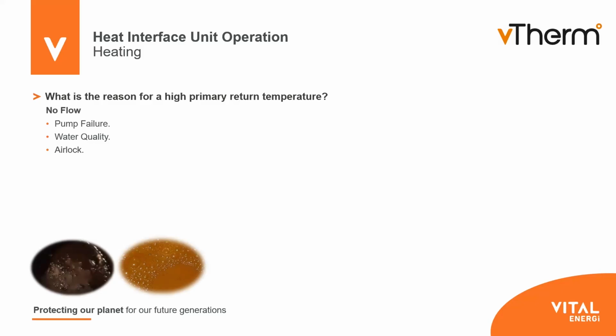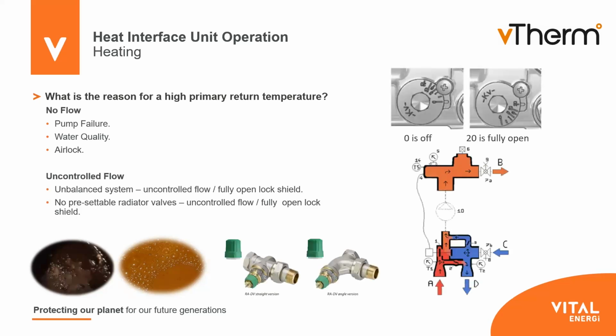And therefore you can see there's different colouring of water content quality. One where the inhibitor has been mixed with the actual flushing fluid originally, and the other one has had no inhibitor, and you can actually see where it's taking rust from all the different pipework. The other thing you'll notice is there's lots of air in the system, and again, that's a detriment.